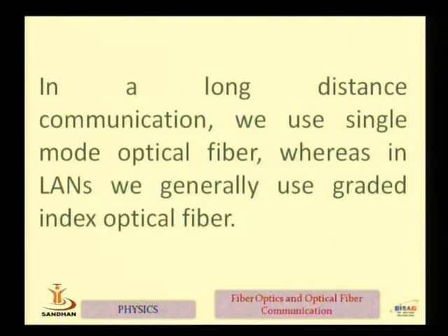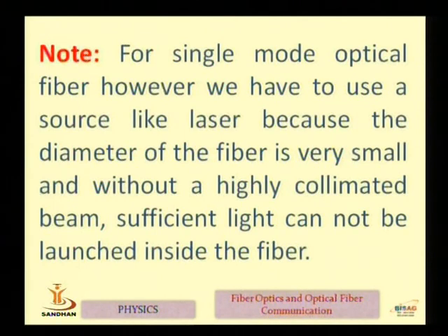In long distance communication, we use single mode optical fiber, whereas in a LAN, or local area network, we generally use graded index optical fiber. Note, for single mode optical fiber, we have to use a source like a laser, because the diameter of the fiber is very small, and without a highly collimated beam, sufficient light cannot be launched inside the fiber.